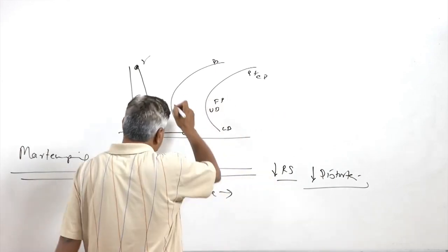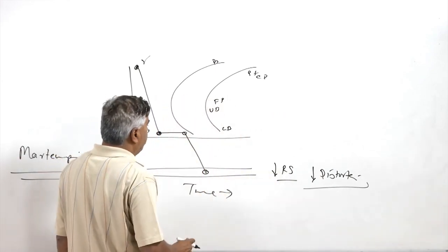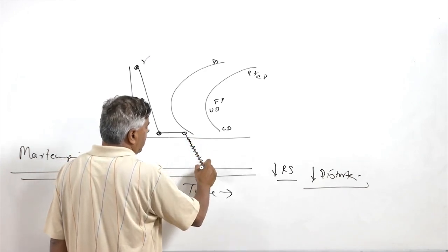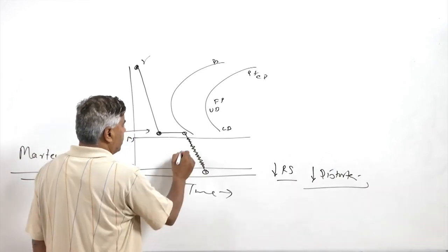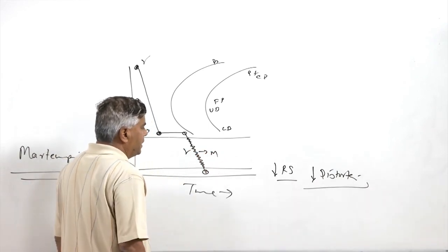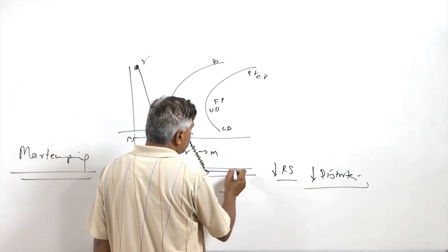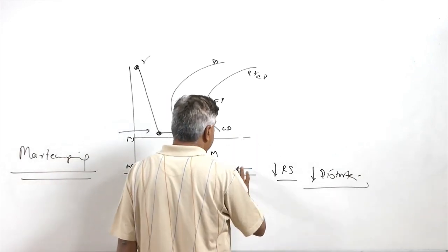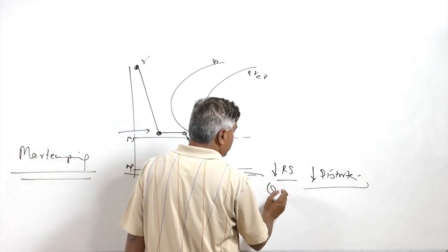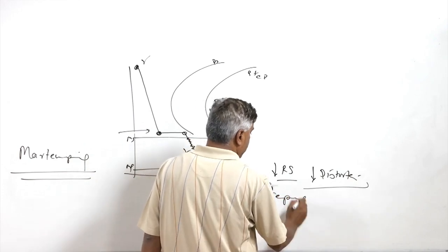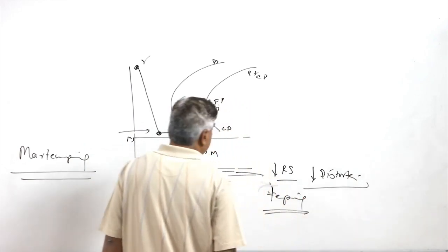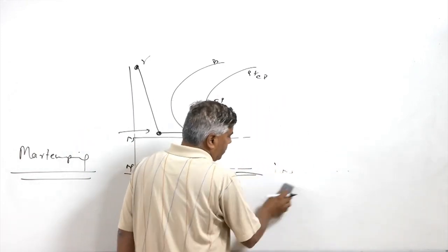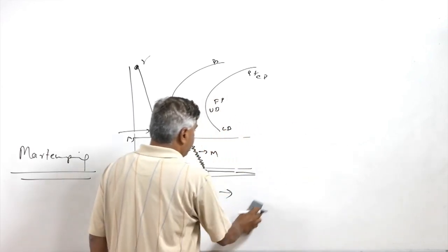So in the second stage quenching, when the sample is taken out and quenched in another bath, then the transformation from austenite to martensite will take place, and after holding at this temperature, the sample is again subjected to heating to the high temperature. So this holding is done basically for the tempering purpose. So the tempering of the component after the Marr tempering is facilitated.